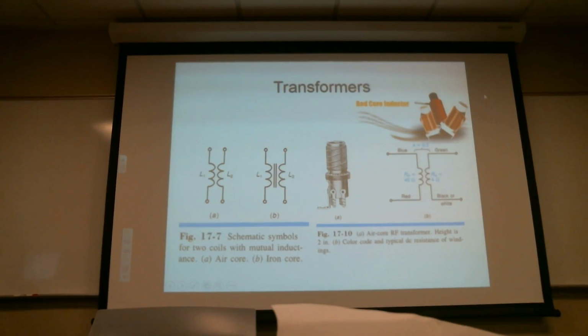We want to laminate it because as the magnetic fields build up and collapse around iron, the magnetic fields are going to try and go into the iron, and as they go into the iron, they're also going to try and induce current going circularly around the bar of iron. Well, if I make it in a bunch of thin plates oriented to the axis that it can go, those currents can only go in a very thin plate this way. So they're going to consume a little bit of energy. Those eddy currents are going to happen, but I've interfered with them as much as I possibly can while still leaving this component permeable.